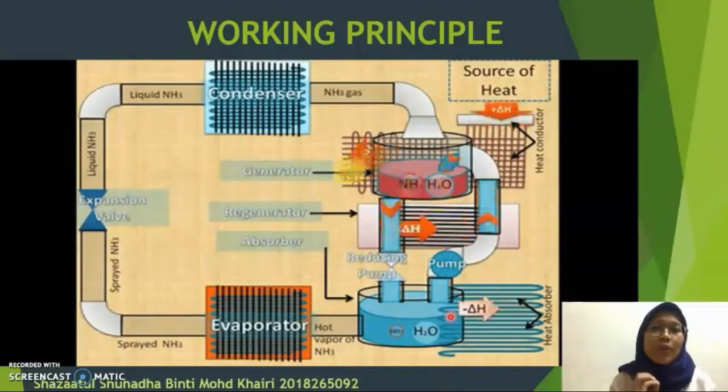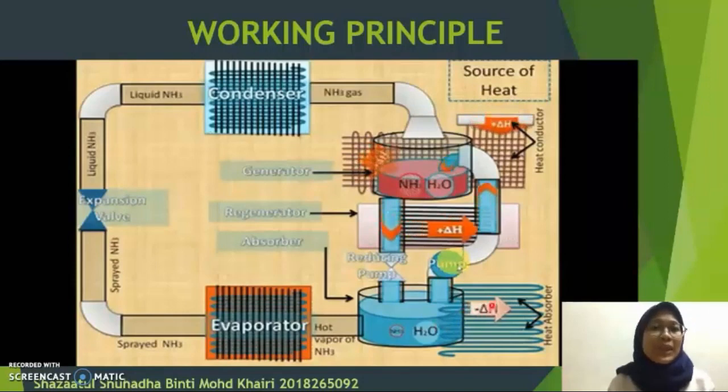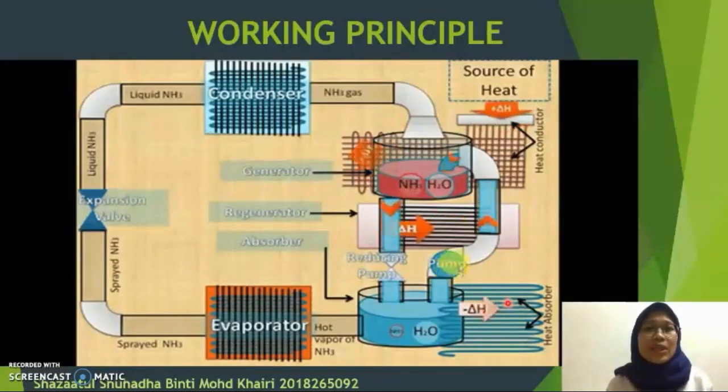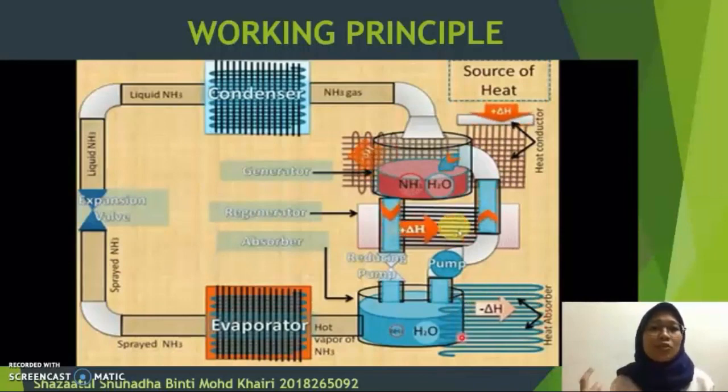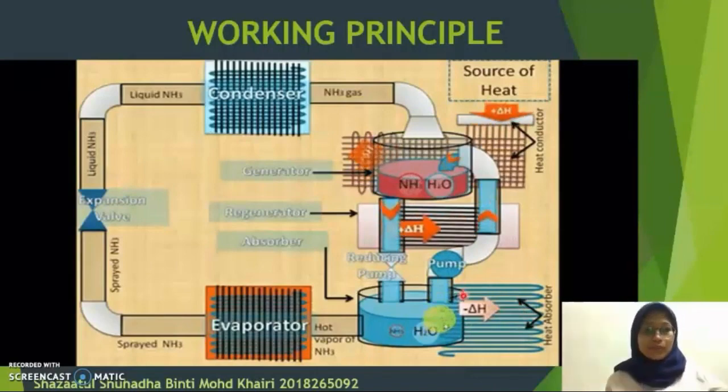When water absorbs ammonia vapor, it also liberates heat that will increase the temperature of the solution. When the solution becomes hot, the capacity of the water to absorb ammonia gradually decreases. So to keep the temperature of the solution at an optimum level, a supply of cool water is provided through this pipe. This external pipe of cool water carries heat away from the solution, and thus the water can continuously absorb incoming vapor.